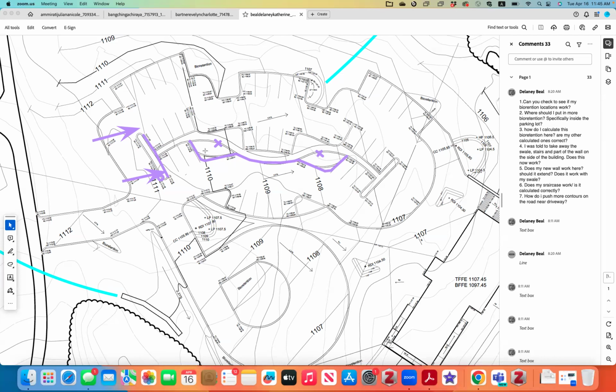Let's see. Yeah, in both of these areas, you could have retention because they are receiving water pretty effectively. Right? You can have a curb cut somewhere here. And then that one, you can have a curb cut somewhere here. And the whole thing would be the retention. And the sidewalk will be just floating above the retention. Does that make sense?